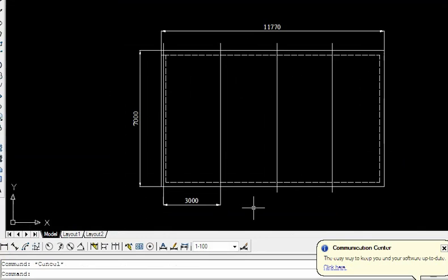First show the outer dimensions, 7 meter by L1.77. Then show the wall thickness all surrounding with 230 mm thick, where we get a support of beams. Next, the beams are being given at regular intervals of 3 meters from center to center. So from this edge it is 3 meter, and 3 meter is for the entire span we have given. 3, 3, 3, 3, we get 12. Every 3 meters is given here.